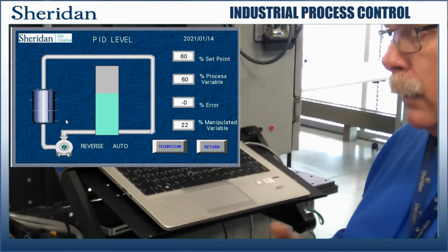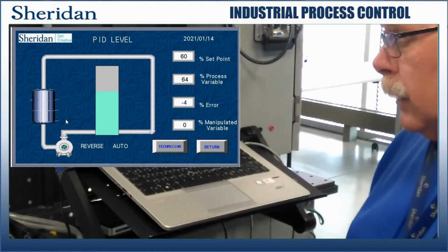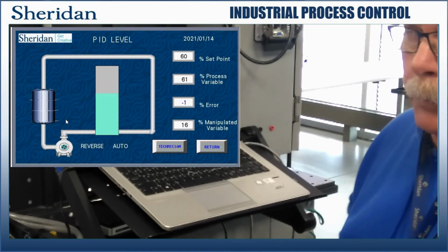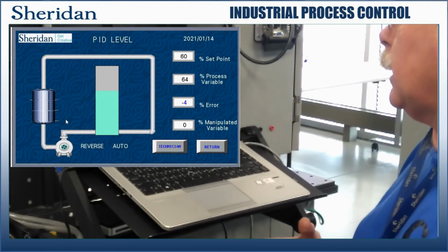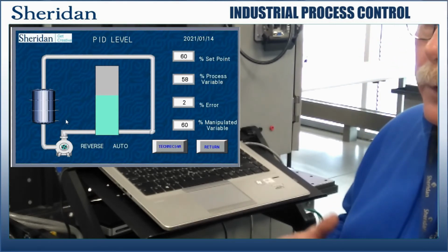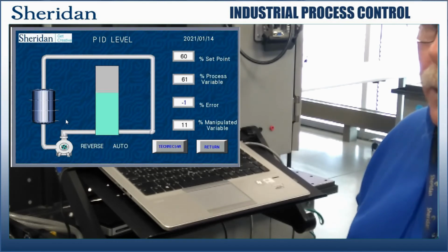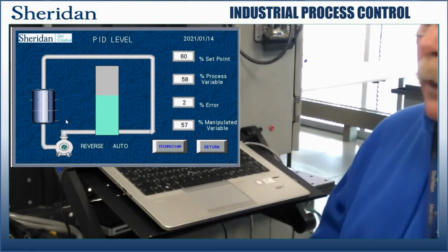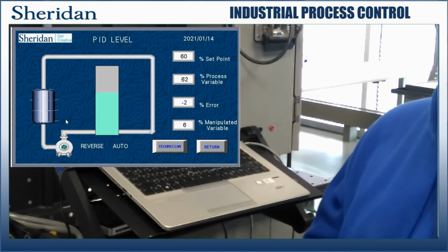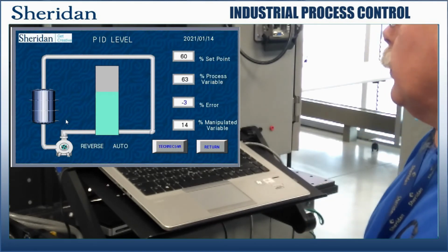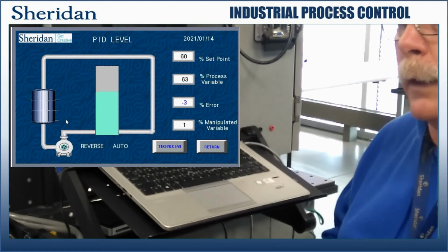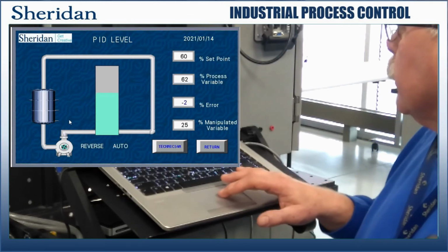Now this can cause a lot of problems in your process. It will wear out your final element. Also too, you have an unstable process. If this happened to be a process that was employing a lot of horsepower, like a 400 horsepower pump, what you'd end up doing is shaking your whole building down. It's not good. Your employer will not like that whatsoever. What you want is a nice, quick responding control, one that maintains a nice, steady process.